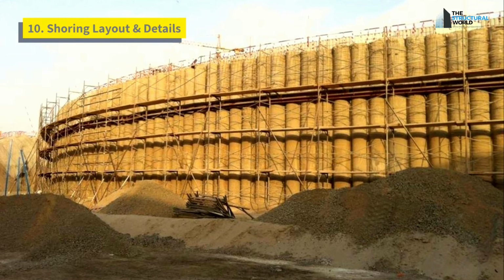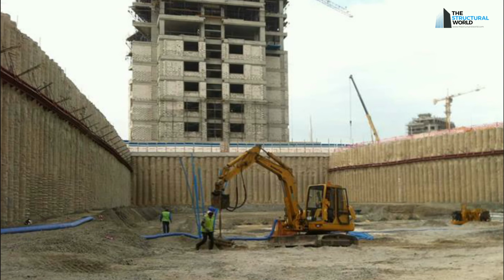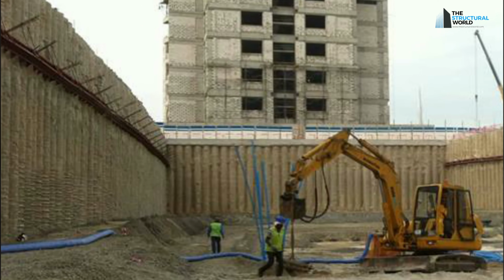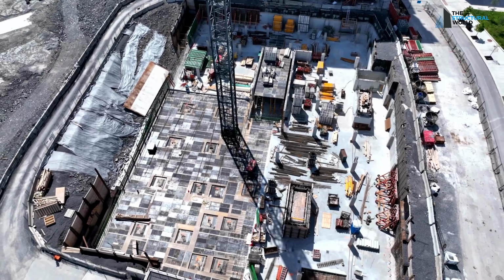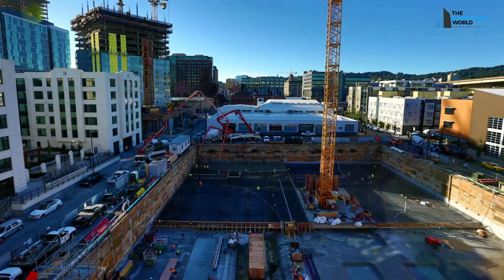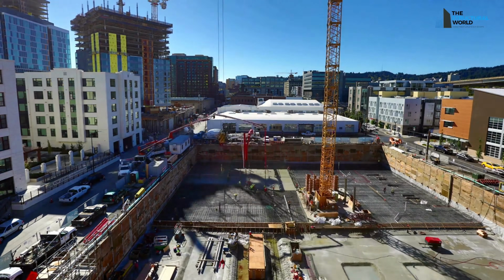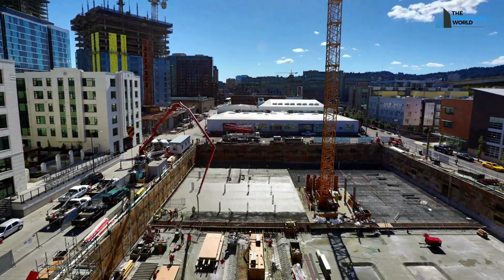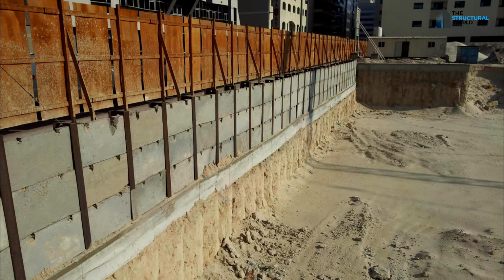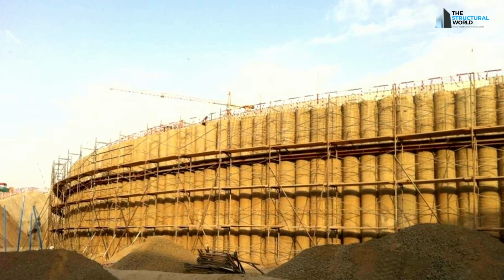Shoring layout and details. A shoring layout sheet can be added depending on the site condition. Shoring layout and details is provided when we need to support our excavation for possible collapse of the existing structure nearby. Additionally, when our proposed project has basement levels, shoring work is a must. When reading this sheet, you'll be guided on where to provide the shoring works in the plan. Whether soldier piles, secant or tangent pile shoring, all the section details have been clearly identified and provided here.